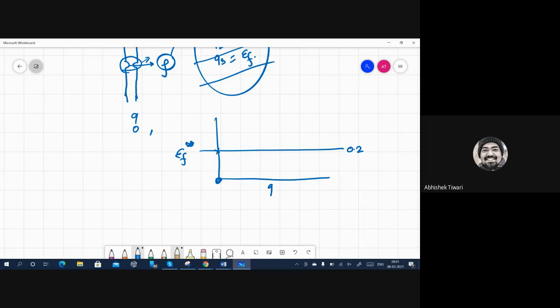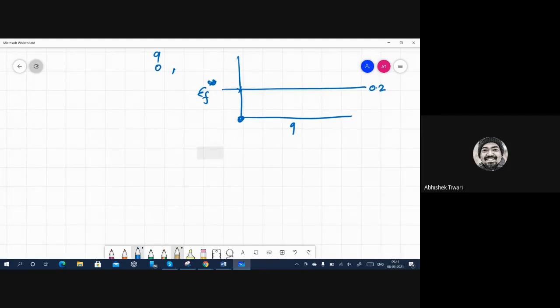So what we will do is, we will provide different values of fracture strain and triaxiality. We will give the same value of fracture strain, 0.2, 0.2. I think only 2 points are good enough. And then here we will give a value of 0 and a value of 10. It simply means that we are giving 2 points on a straight line which is parallel to the Q axis. That means it is independent of the triaxiality. So whatever is the value of triaxiality, the fracture strain is not going to change.